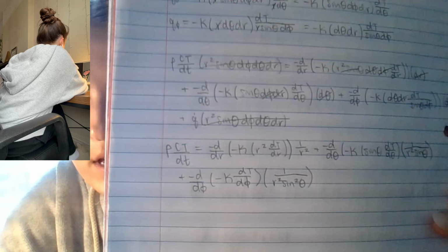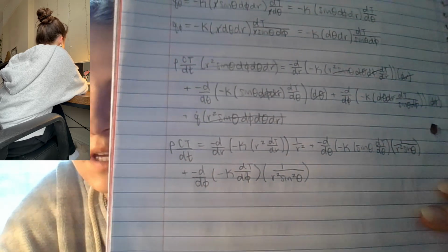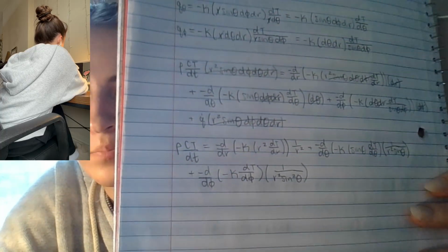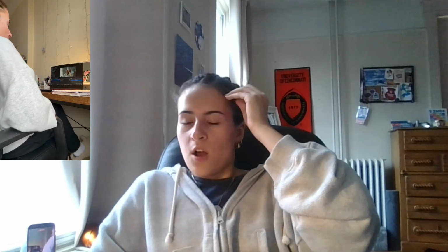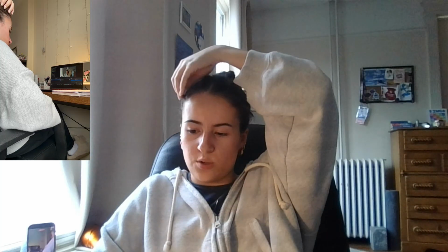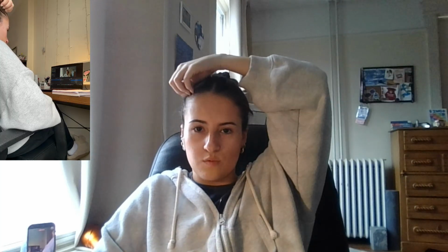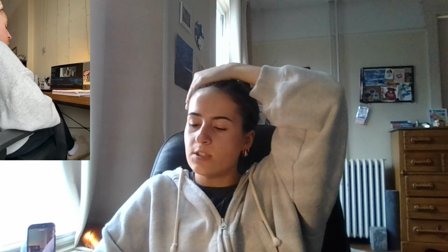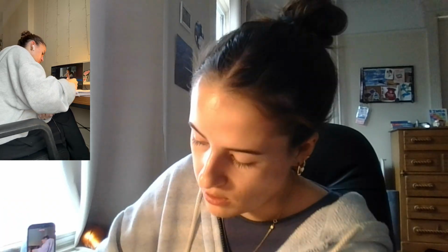So those are all 3 of our net heat flows after canceling out the volume. That's what they end up looking like. And finally, we have to add back our energy generation, which at this point will just be q dot, now that we've taken away the volume. So our next step now is to divide by rho C in order to be solving this equation in terms of changes in temperature over changes in time. So we'll go ahead and do that.